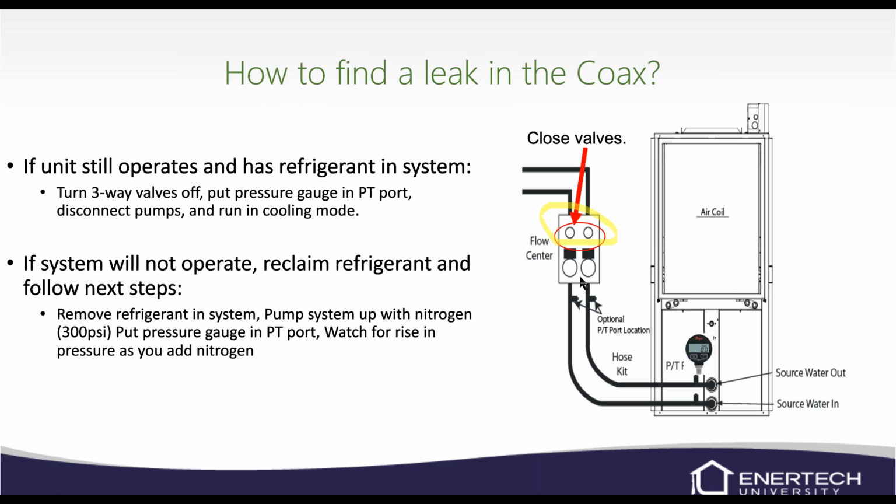With the pumps off, the pressure is not going to really change. It shouldn't. So once we start to build that discharge pressure, if we think the leak's in a heat exchanger, it's going to push that refrigerant into the water. So in turn, if we had 20 PSI pressure on this pressure gauge, then that pressure is going to start raising. If you see it start raising, then we know there's a leak in the heat exchanger, and it's pushing the refrigerant into the water.